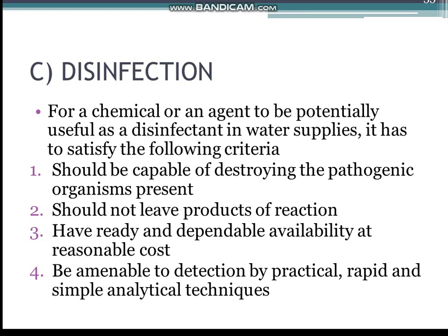Second, it should not leave products of reaction which render the water toxic or impart color or otherwise make it unpotable. Third, it should have ready and dependable availability at reasonable cost, permitting convenient, safe and accurate application to water. Fourth, it should be amenable to detection by practical, rapid and simple analytical techniques in the small concentration ranges to permit the control of the efficiency of the disinfection process.